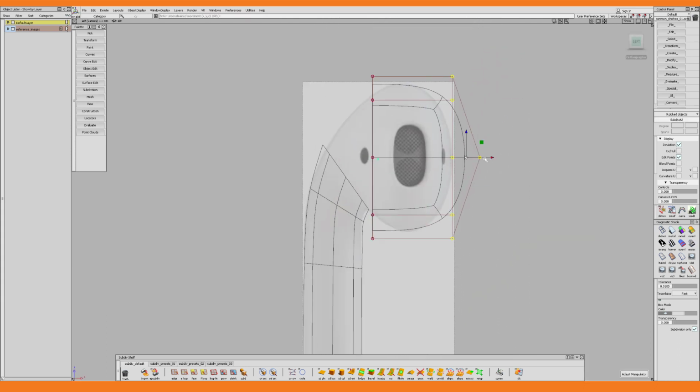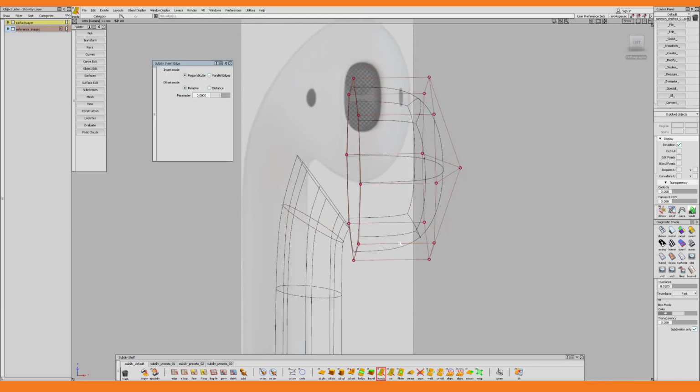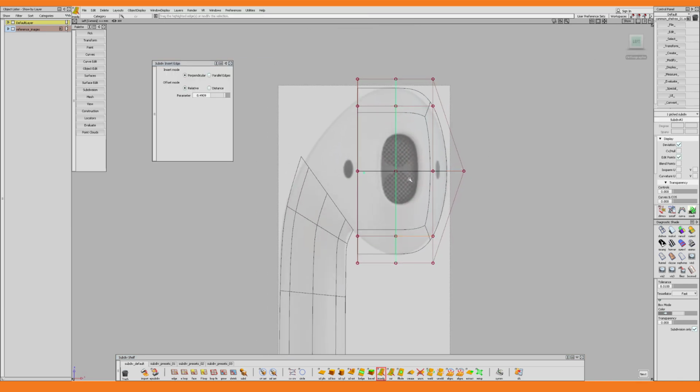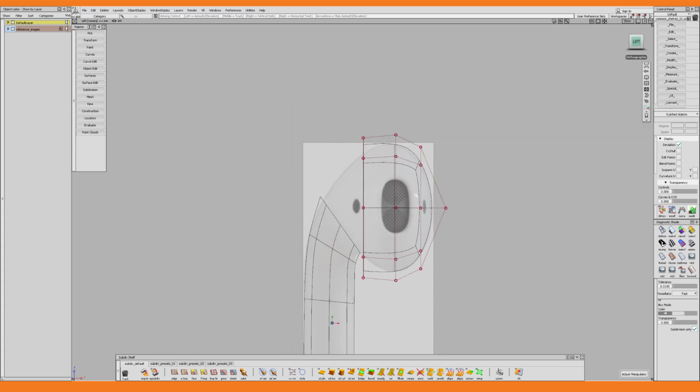And then it's back to the side view for some more modifications. To be able to better match the shape, I need some extra geometry, why I insert an extra edge loop in the center. Now, with all the necessary geometry in place, it's just a matter of moving, rotating and scaling vertices until I'm happy with the result.